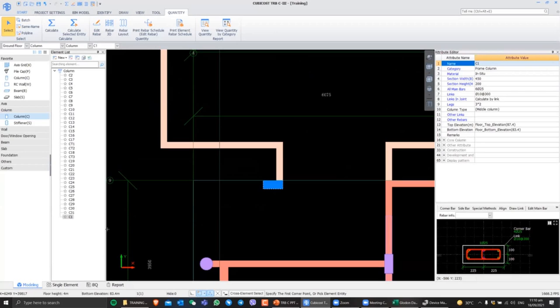Now, if you want to further edit your C1, go to the rebar info below. Dito po sa pinaka-ilalim. Rebar info. And then press these two buttons right here, no? Switch to multi-section, press this, and pop out edit section. Okay, just press these two buttons right here.